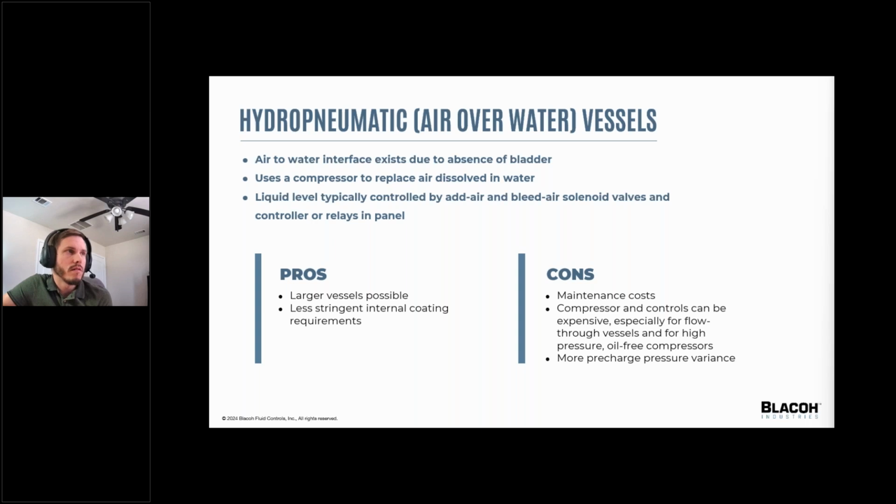But for high pressure and oil-free compressors, your price can get pretty high, and in some cases we've seen it be as high as the vessel itself. And especially for flow-through vessels, as opposed to teeing the vessel into the line, because you have much more water turnover, so you have a much higher dissolution rate.